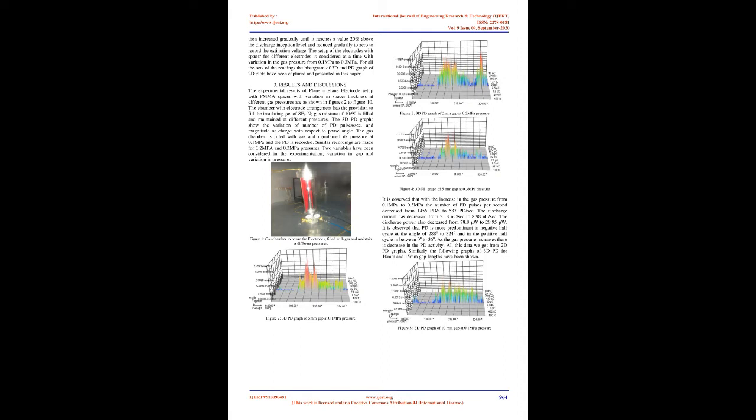The breakdown of the insulation system causes the need for costly and time-consuming maintenance, as the whole unit of insulation needs to be replaced. To avoid this, PD measurement and PD data analysis are essential to assess the performance and condition of the insulation system in order to avoid unwanted breakdown [7 to 11]. The PD is measured at variable frequency of the applied voltage. The added advantage of this method is that local conditions at defects in the insulation change with the varying frequency. As a result, with the change in the frequency, the PD activity also changes.